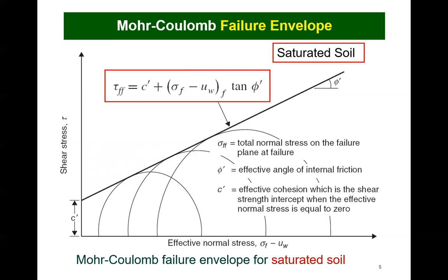There are other shear strength equations that have been written for saturated soils. However, the intent of this lecture is to build on the classic form of the shear strength equation for a saturated soil. Mohr circles can be plotted using the effective principal stresses, and their limiting extent become tangent to the failure envelope for the saturated soil.